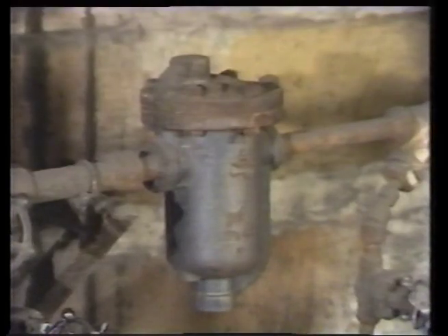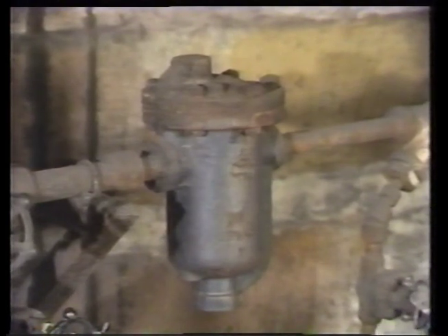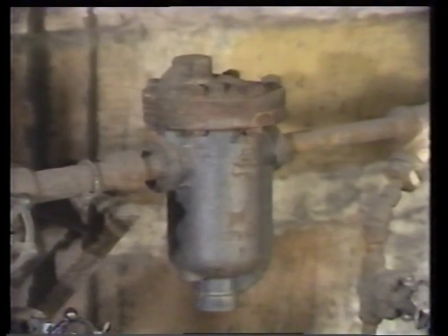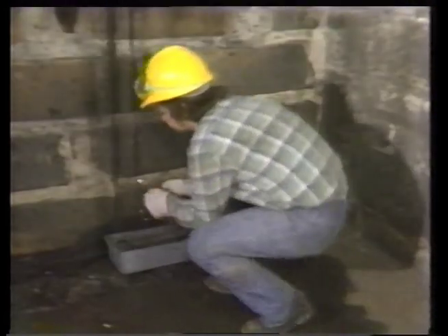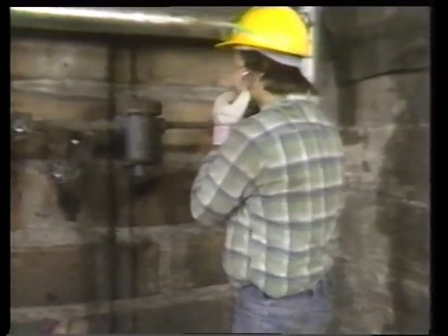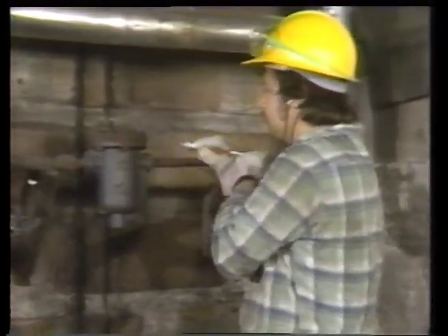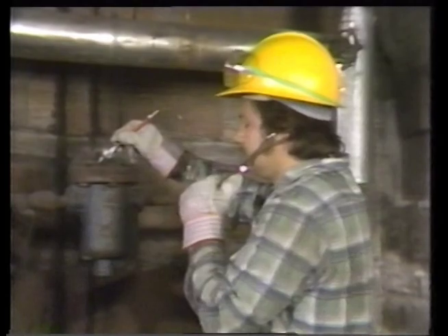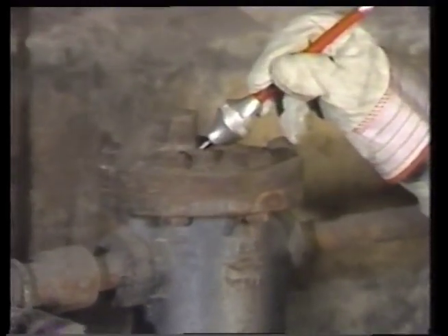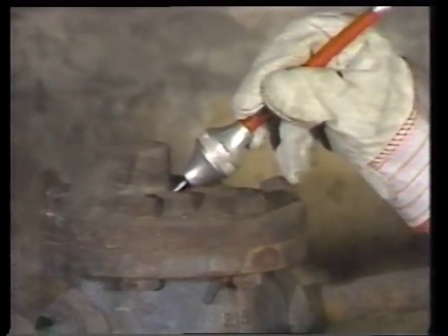And if the trap doesn't discharge to atmosphere and there is no test connection, then you won't even be able to make a visual inspection. You may want to inspect the trap by listening to the sounds it makes. An instrument of some type is helpful in transmitting the sound from the trap to your ear. A sounding rod or even a screwdriver will work all right, but a stethoscope is probably the best tool to use. Place one end of the instrument on the trap body and the other at your ear.